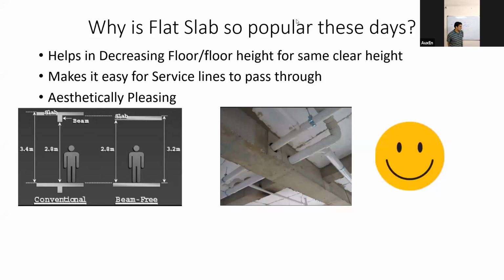The third issue is that many times you may cut a stirrup or a ring when you are cutting the sleeve. So this is also not a very good issue. Another issue is that when you are making a sleeve, there is a stress concentration observed where you have reduced the concrete area. All these issues are a big headache for us when we are providing sleeves.